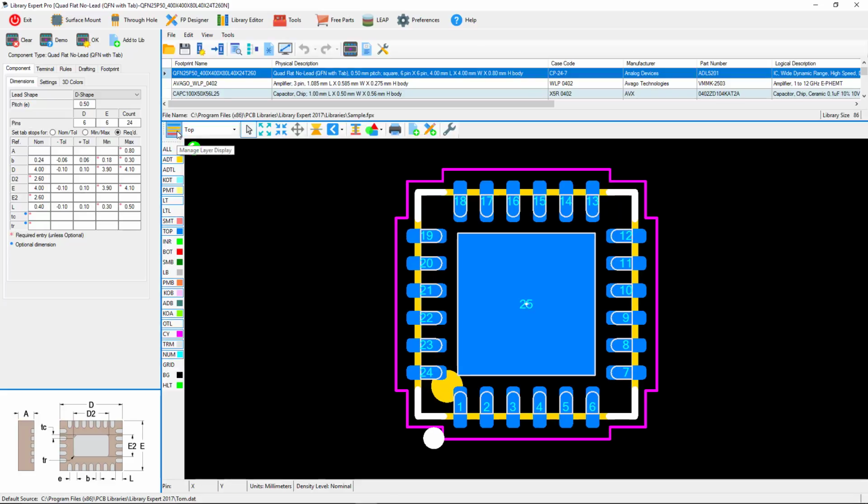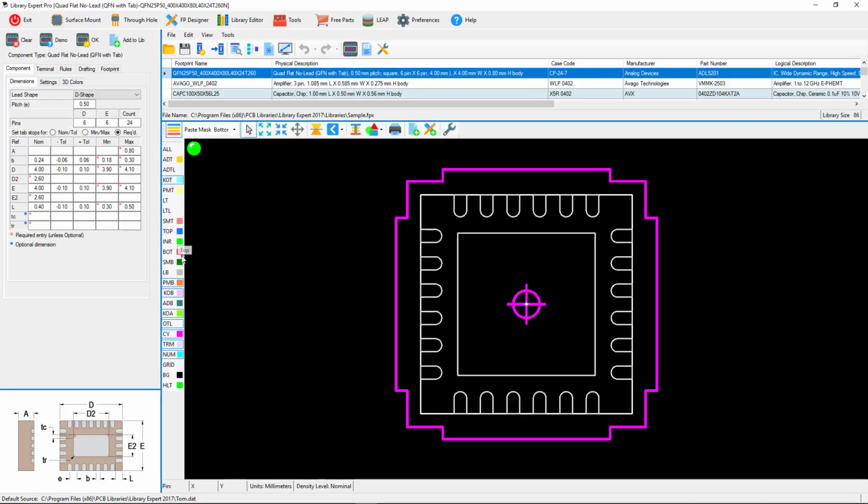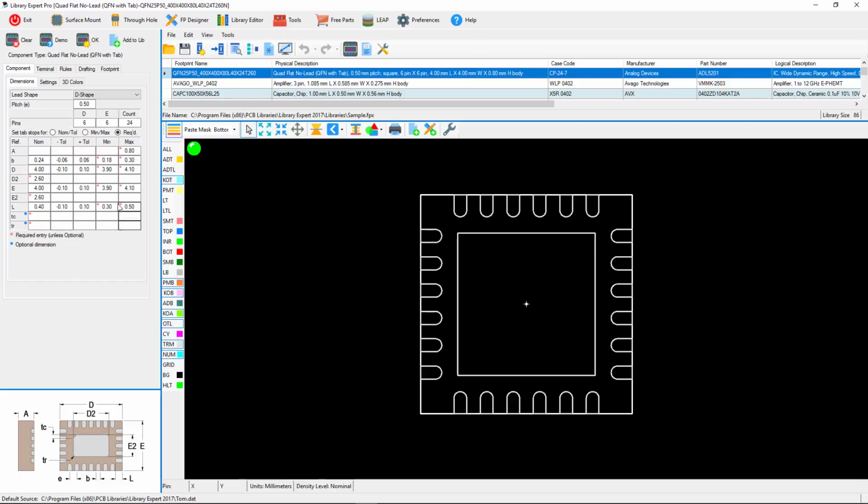If we turn off some layers, you can see here that the component dimensions in the panel derived the component package body outline, the terminal lead width and length, and the thermopad. This is the basis for starting the calculation of the footprint.